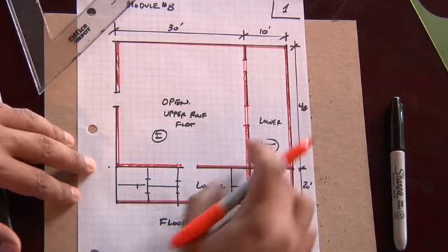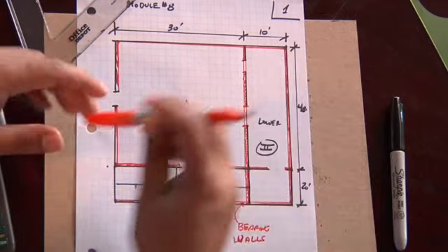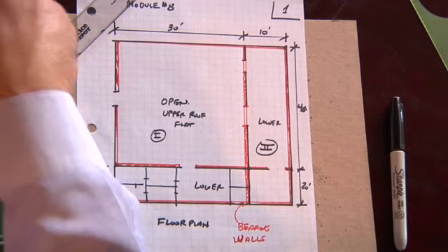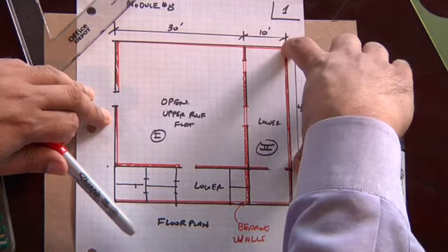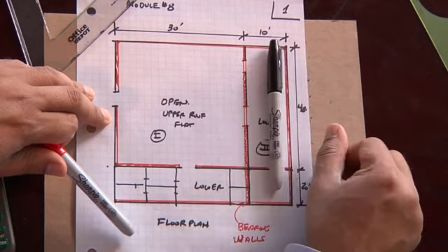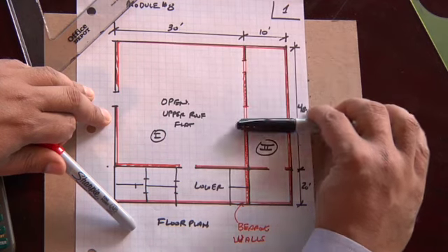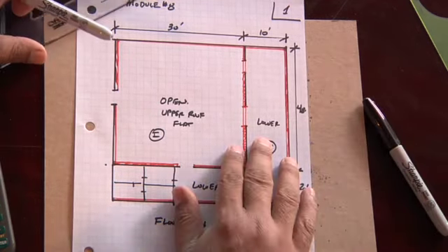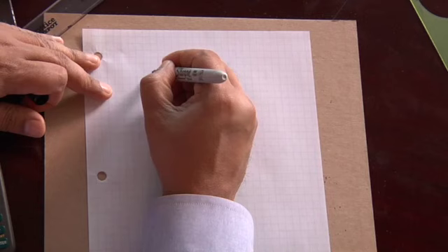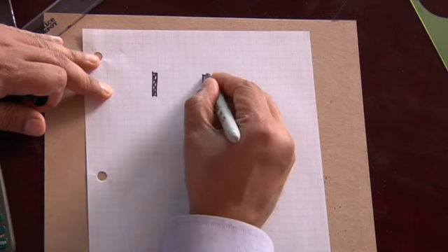So now that we see that, the lower plan, let's do this part first. The lower plan is a rectangle. We have a 48-foot distance in this direction. And so to lay out joists in that direction is really not a responsible way to do a plan. It stands to reason that the joist should be laid out along the short span. And I don't think I need to do a big explanation on that, but I'll just give you a very short version of an explanation that obviously if you are doing any type of structural design and you have 2 bearing walls which are spaced 10 feet apart,